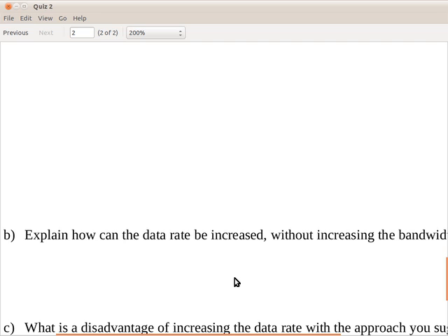What's the problem of doing that? More errors are possible. More levels, the more chance that when we really have noise, the receiver will make a mistake. It will measure at minus 3.7 or plus 3.7 volts, because there's noise, and then it maps it to this value when in fact it was this value that was transmitted.